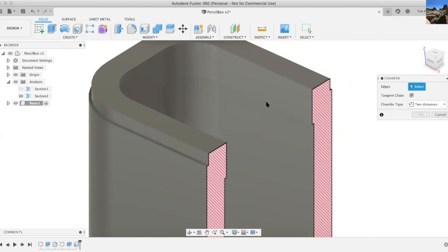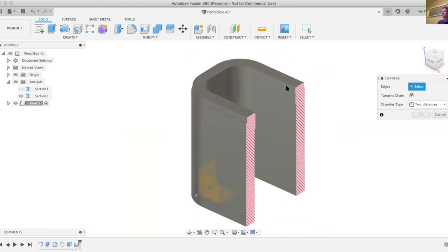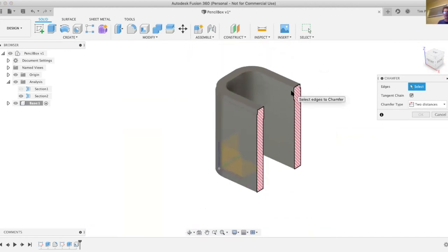Right? So it does not include like perpendiculars? Correct. It's just tangents to a line. Okay, good. Correct. So, for example, if we didn't have the fillets in here, even with tangent chain, it would only take this up to the corner, one line up to the corner. So the concept of tangent chains is very useful. There's a lot of times you use it.